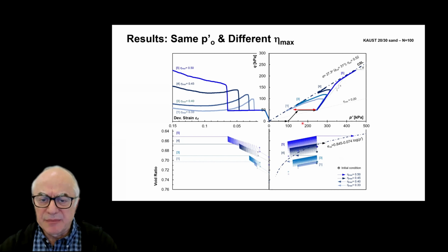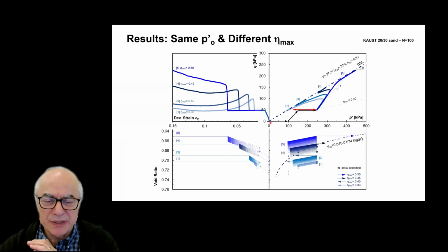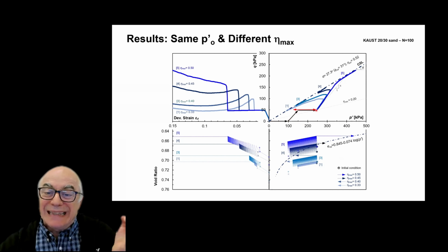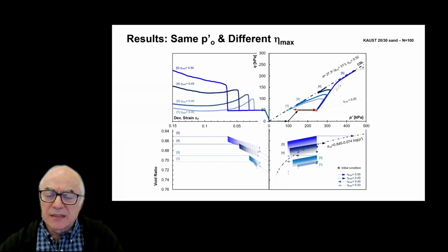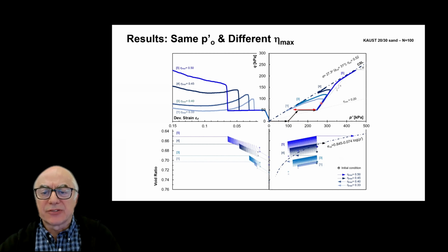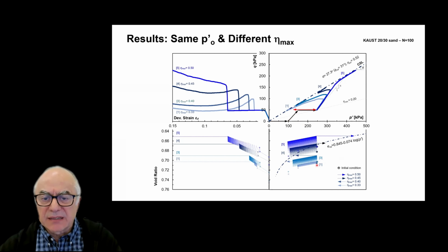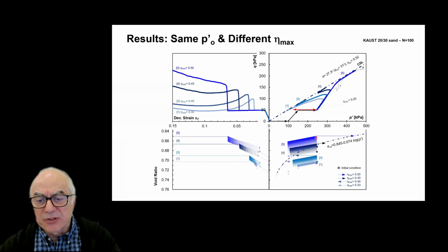This is a little bit of a complex plot because we are showing the whole data set, which is the isotropic confinement, drain, the deviatoric loading, then the cycles of pressure. And at the end, we conclude the test by a monotonic and drain conditions. So notice that we start the test 1, it was very loose, and we go to different conditions, starting from below critical state, in other words, a dense test.